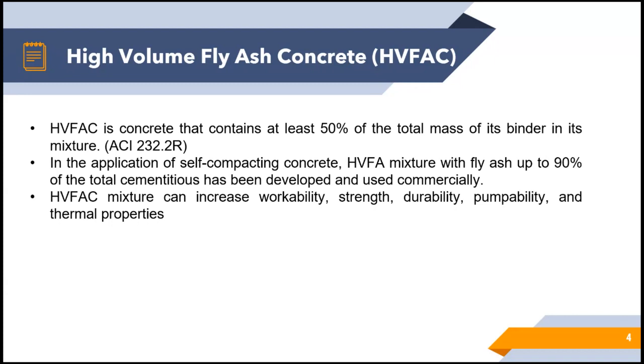In the application of self-compacting concrete, high volume fly ash concrete mixed with fly ash up to 90% of total cementitious has been developed and used commercially. So many countries use fly ash in high volume for concrete. High volume fly ash concrete can increase the workability, strength, durability, pumpability, and thermal properties.